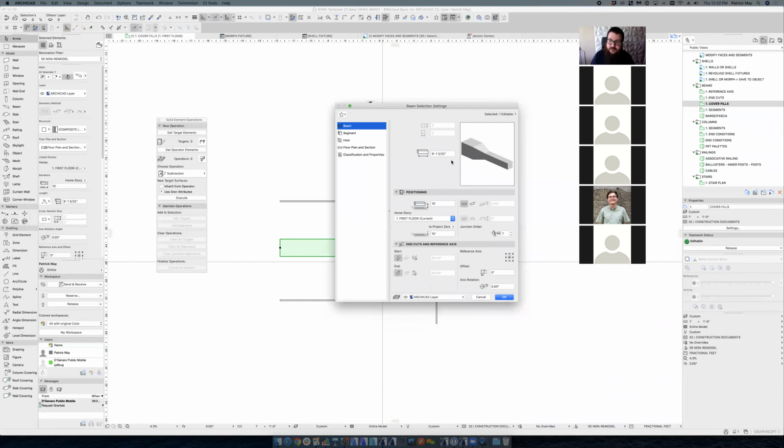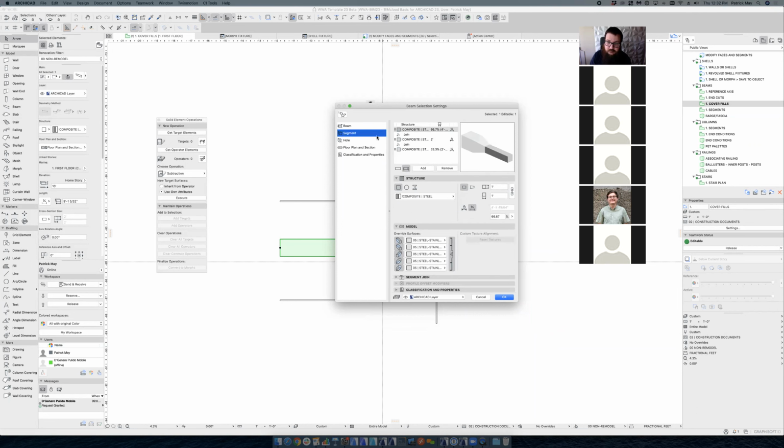The thing I like the segmentation for is the opportunities to model ductwork if we end up doing that modeling instead of our consultants. Fortunately, more and more of our consultants are doing the MEP modeling for us. But if we do end up doing the modeling, it's as simple as basically taking a single run of a beam, and you can add any number of segments to it. You can see the segments being highlighted here.